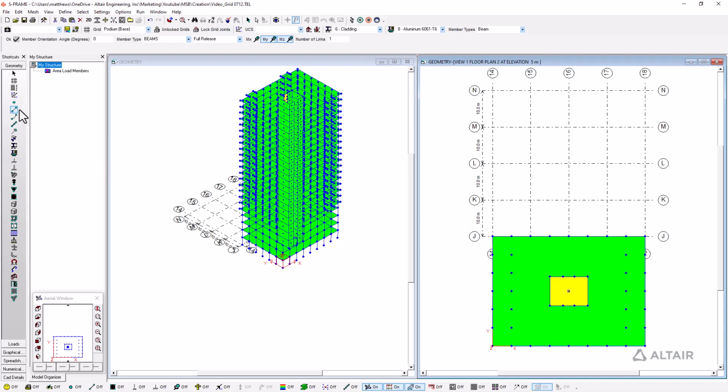And we're starting to see some repetition in the tools that we're using. We're going to have a composite steel structure representing our podium. And to do this, I'm going to use the member definition tool to lay out my columns. So I'm going to change the member type to columns. I'll change the section type to this Y-plan shape. And I'm going to use a steel material as well. And it's just a matter of essentially laying out the column geometry.